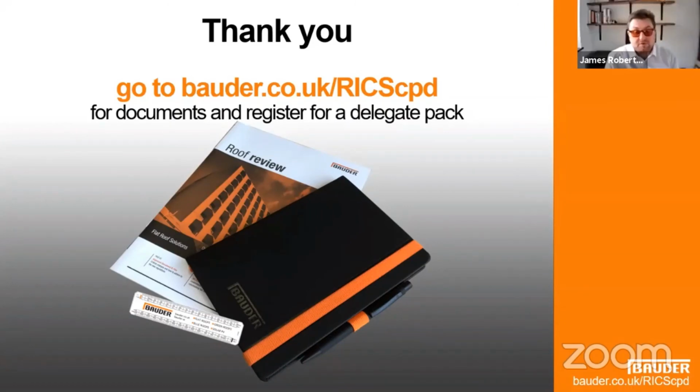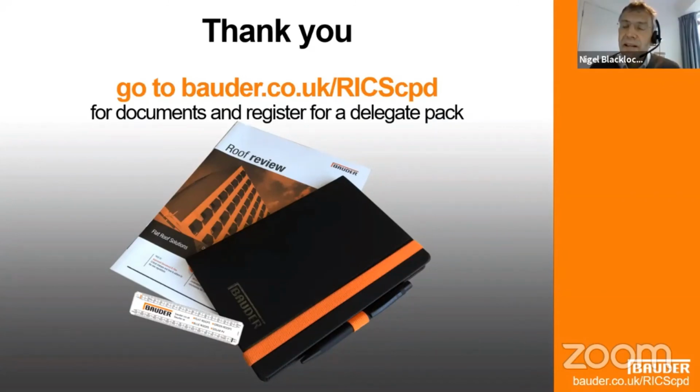Next one: a lot of work has clearly gone forward to develop this new legislation after Grenfell. However, with regards to existing flat roofs, are there any areas that landlords should be checking during PPM? Existing roofs, so we're talking about existing landlords, I take it. In the end, the regulations for flat roofing, and that was one of my earlier points, the flat roofing guidance really hasn't changed. Approved Document B brought in some unintended consequences because it was intended to exclude roofs, but unfortunately a lot of the points I've had to raise are where it's maybe brought them in, or people thought it had brought them in, but they are exempt from it.